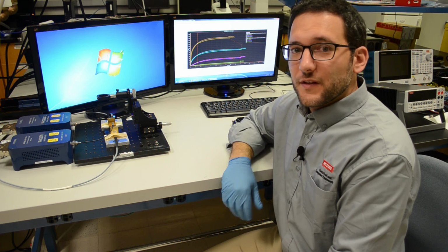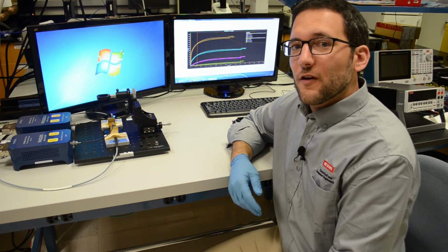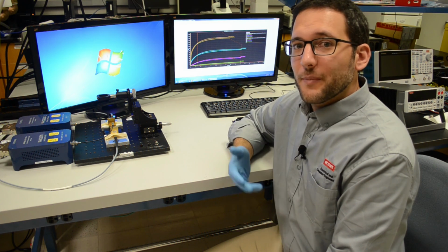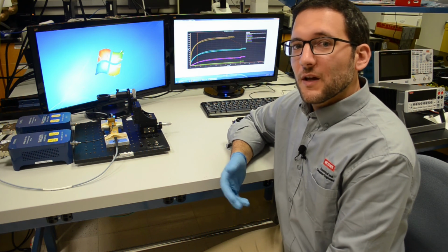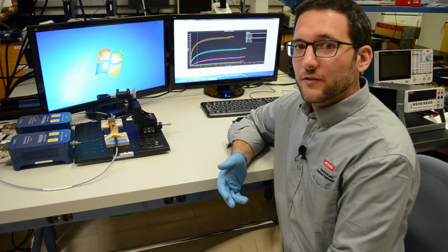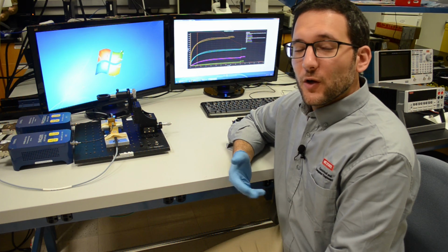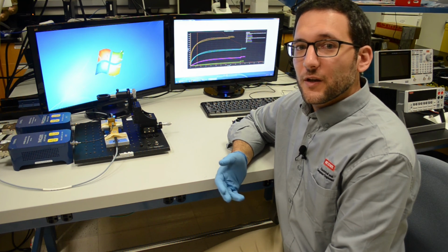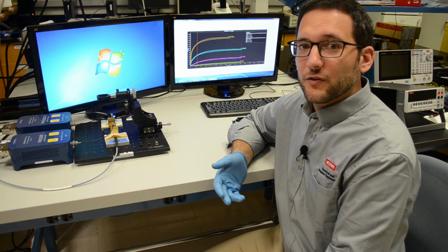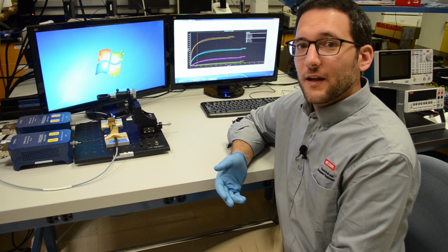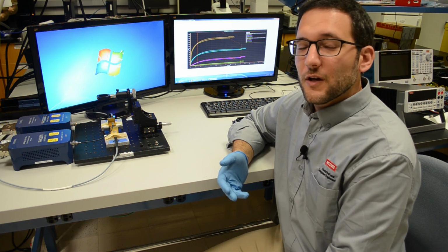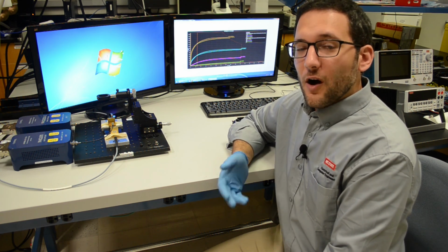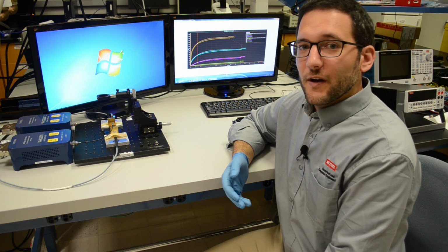This concludes this demonstration. Today, we started off by looking at how we can test power devices on wafer by using a combination of a probe station and a semiconductor parameter analyzer. This allowed us to look at the low voltage behavior of these devices first and confirm, for example, where the threshold voltage is. In the case of an AlGaN-GaN HEMT, we confirmed that by using a recessed gate structure, we can achieve normally off behavior or an E-mode type of device.